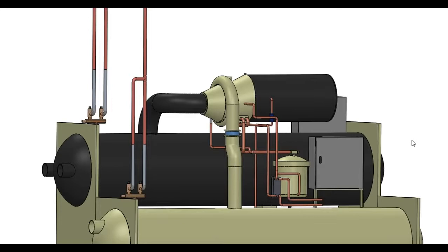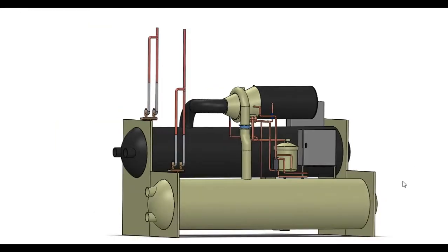and obviously we're going to look at each of these components in much greater detail in further videos, but for now let's just apply each of the 4 components and try to work our way around the chiller to see where each of these are actually located, and transfer that knowledge from the illustrations to the actual model. So you should be able to, by the end of the video, tell me, or tell yourselves, where each of the 4 components of a chiller are. So as I was saying, there's the compressor up on the top there with the electrical motor mounted on the back there.